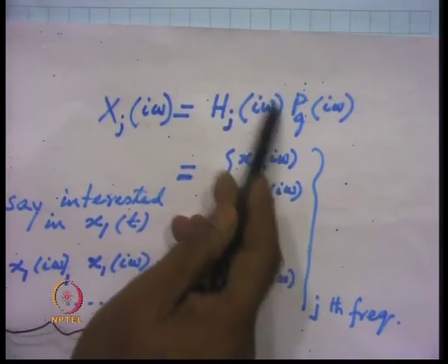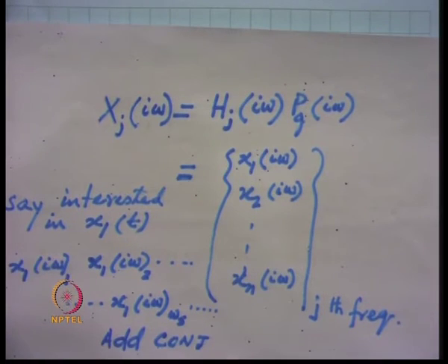The H(i omega) matrix is in fact the inverse of the matrix K minus m omega square plus i C omega, which is the same kind of expression you have for the single degree of freedom system, only you replace K, M and C by the K matrix, M matrix and C matrix.